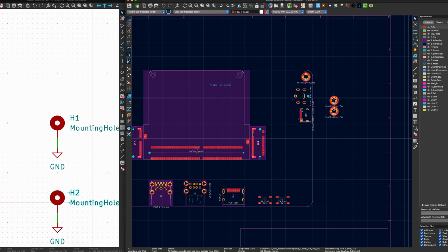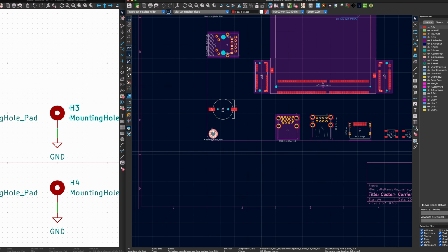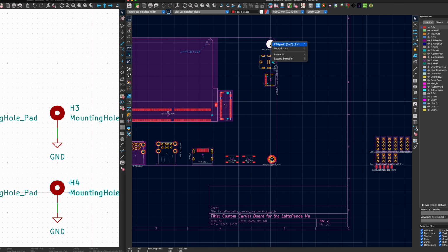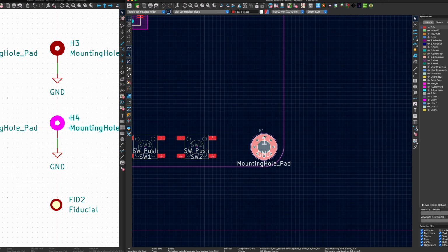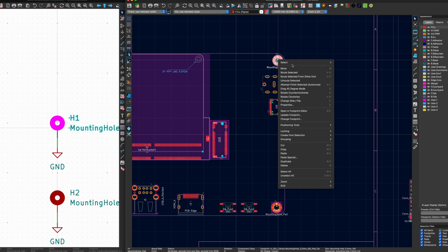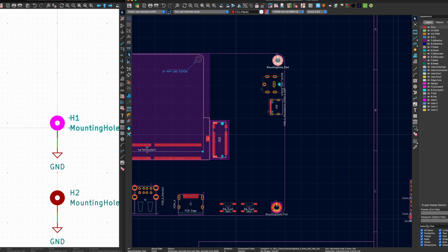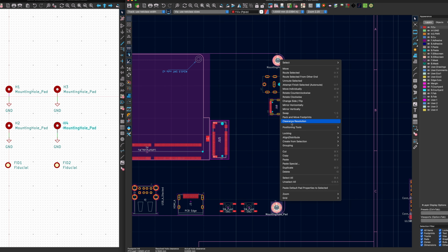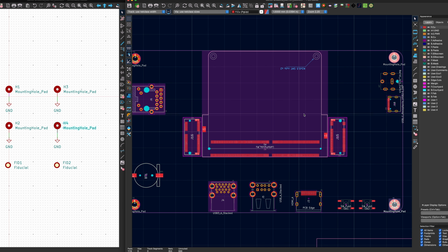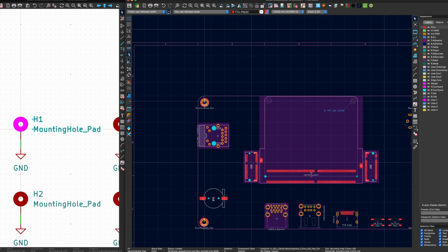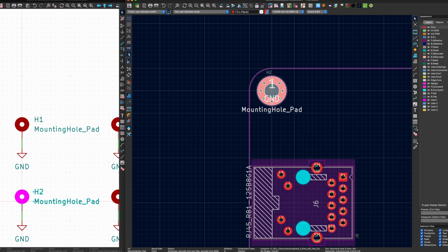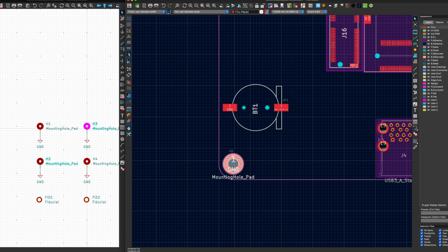You'll also learn how to manage copper effectively to ensure electrical performance and thermal balance. This includes creating ground and power fields, optimizing thermal reliefs, and understanding how copper geometry impacts impedance and EMI. We'll study both the reference design implementation and your own optimized version, highlighting how thoughtful copper management contributes to reliability and performance.